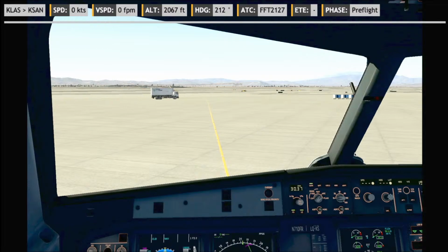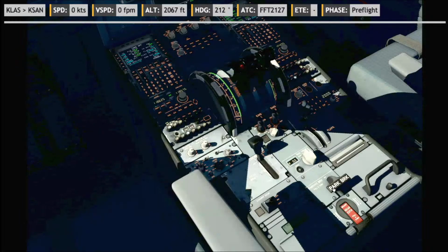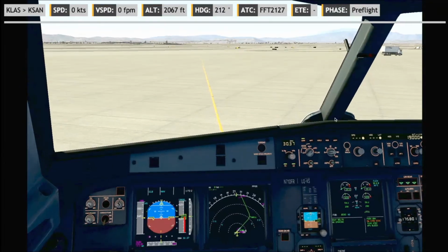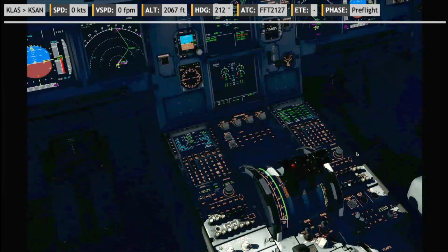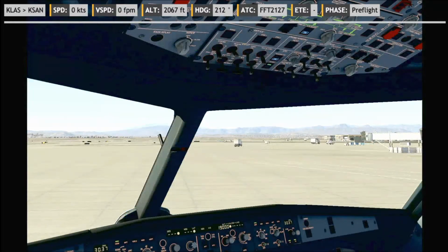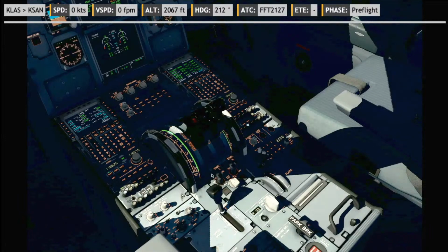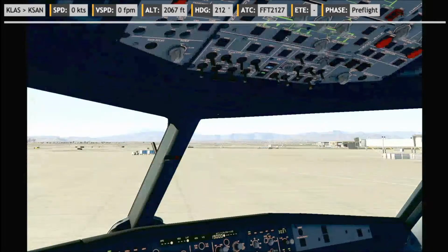Operation complete. Set parking brake. Alright. Parking brake set. Disconnecting tow. Stand by. Roger. After start checklist. Engine mode selector is normal. APU bleed off. Speed brakes armed. Flaps, I will wait for flaps. We'll go auto brakes max. Anti-ice not required. And APU switch off.